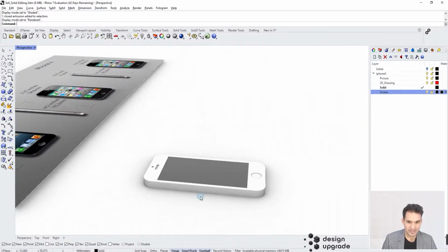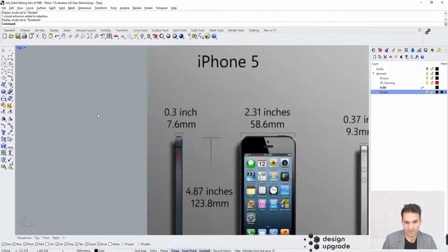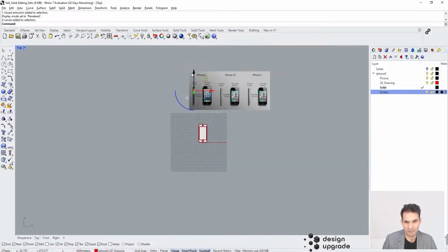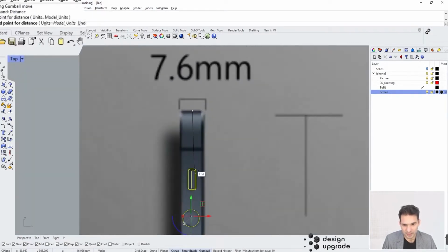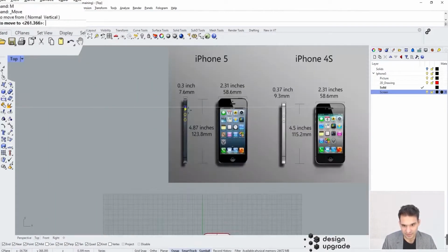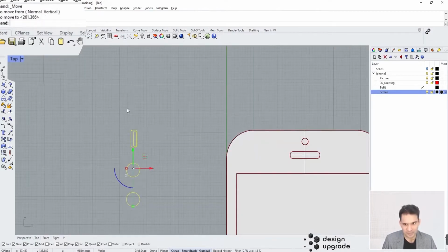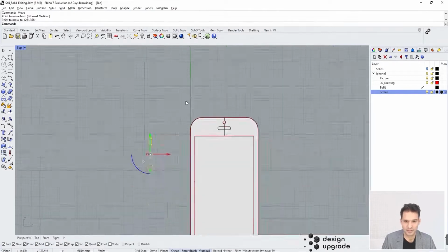Now let's look at the sides. For the sides, we actually have this geometry, right? I'm going to take this one, move it. I'm going to first measure from the upper scale how much it goes down. It's about 17. All right, then I can just take everything here, move it down, position it to my top, gumball minus 17. That should do the job.